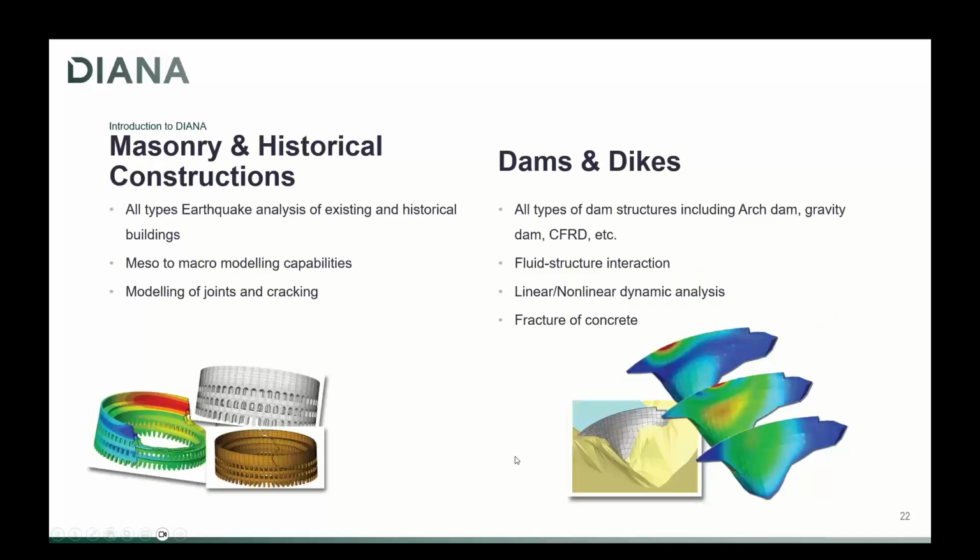Among other applications, we can refer to masonry and historical constructions. In Diana, we offer different solutions at meso or macro levels. You can use Diana to model the interaction between the individual bricks and the mortar joints, so quite detailed.